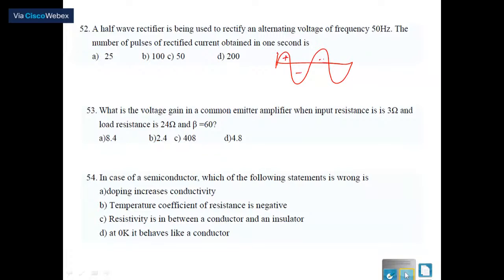Well, what is half-wave rectifier? That is one of the types of the rectifier in which AC will be converted into DC during only half cycle of AC. Well, so during the positive half cycle, the signal will be converted into the DC. Well, and the next half cycle, the diode D becomes a reverse bias, and in the reverse bias, there is no current through the load resistor, so therefore there is no current. Okay, next, once again in the next option, so when the positive pulse appears at the end, well, negative pulse appears at the other end of the transformer, secondary transformer, and the diode D becomes a forward bias and current